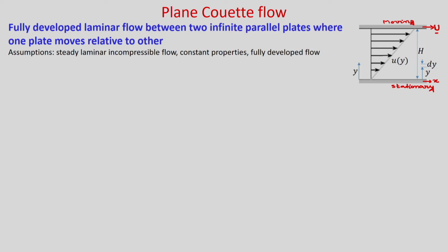That is why we call it plane Couette flow. Where you have an external pressure gradient as well along with the shear driven flow, then it will be Couette flow, but here we are considering plane Couette flow, where we are assuming that the pressure gradient is 0. So, in this particular case, we are considering minus dP by dx as 0, and fully developed condition.